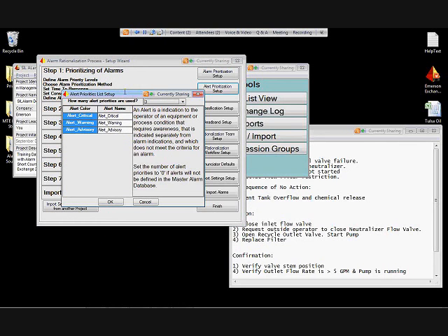Now for this particular customer, this particular philosophy, they've decided that system and instrument diagnostic alarms should not be presented as alarms to the operator. They should instead be treated as alerts and sent to the maintenance department. They'll be available for the operators to see, but that information will be segregated from the alarm information. So we're going to define 3 different priorities of alerts: critical, warning, and advisory. These would probably correspond to priority numbers 4, 5, and 6 in the DeltaV system. So that's set up.